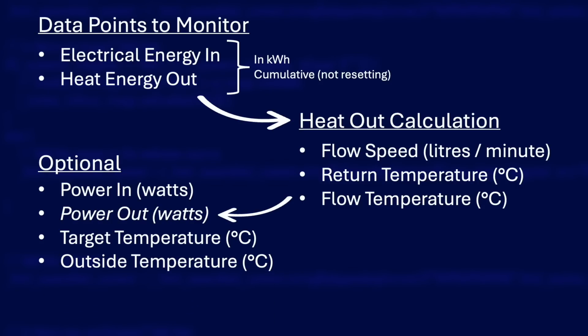You should probably monitor the outdoor temperature too, because that provides some context to the data on a particular day. You might see your energy use rise dramatically one day, for example, and knowing that it was due to it being very cold that day is an important detail.